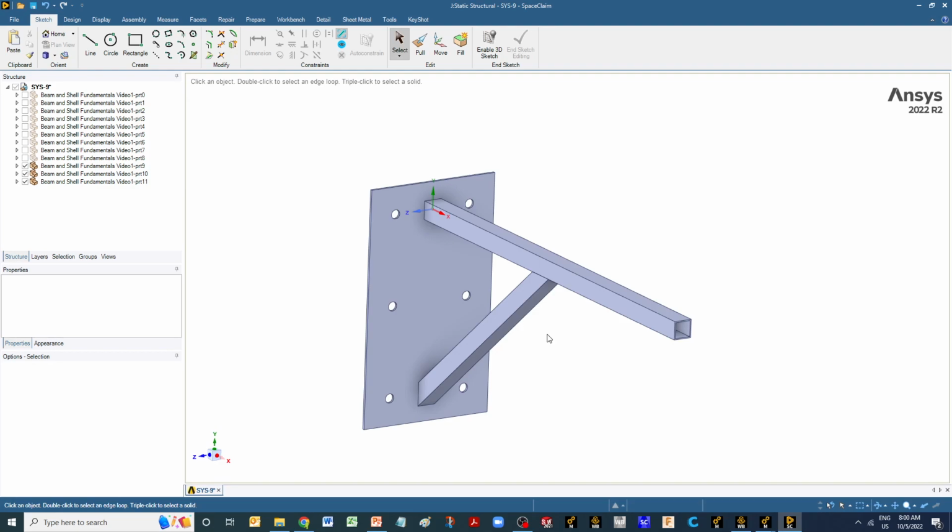But if I'm coming up with a new structural concept, I will basically start with a simplified model. I don't need these details because I don't even know, this is not an existing design. I don't know the forces involved. I actually have to find these forces and loads. So I can start with a sketch. I can do some hand calculations, and that is highly recommended.